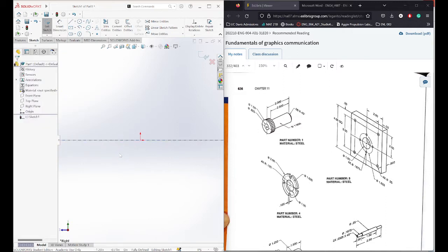I always make my center lines horizontal because it'll help me easily find out which one I'm revolving around. So in some cases, you have multiple center lines or hidden lines inside a sketch, so you want to always know which one you want to revolve around, and this will help me do that. It would also be easily visible over very big sketches.